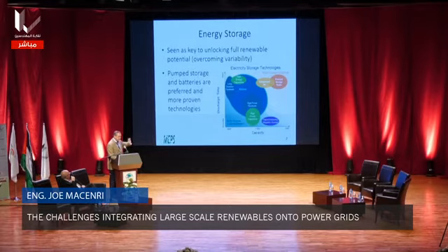So that's an old technology. It's been around since the 50s, 60s. It's well known. It does not have great energy efficiency. The round-trip efficiency in pump storage is a little better than 50%. There's quite a lot of losses in hydraulic losses. The preferred technology would be batteries.